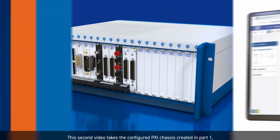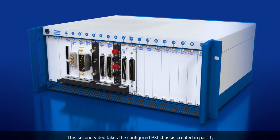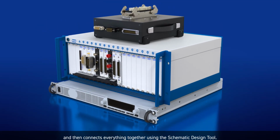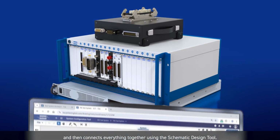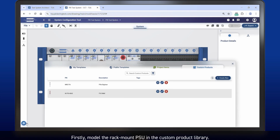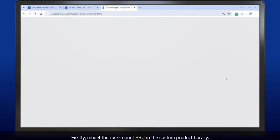This second video takes the configured PXI chassis created in Part 1, adds a rack mount power supply and DUT fixture adapter, and then connects everything together using the Schematic Design Tool. Firstly, model the rack mount PSU in the custom product library.